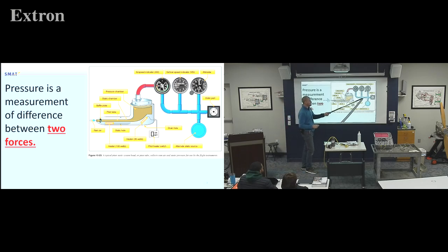In our static system, that's the side we can run a vacuum on by covering up this hole, run a vacuum and then stop the vacuum and say, is it holding? And what we can watch is our altimeter. If I put a vacuum all the way to 30 inches, I would be in space, right? I don't know what altitude space is, but we would be in space. We don't have to go that high. So we're just going to do a small vacuum and we'll cover it later. We'll do maybe 1,000 foot of altitude vacuum. So we'll run our altimeter up 1,000 foot, we'll cap the line, and as long as our altimeter stays there,